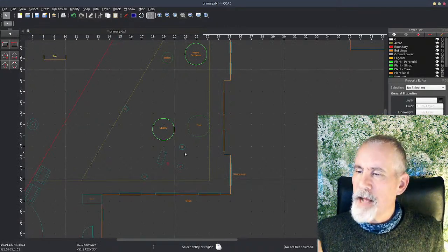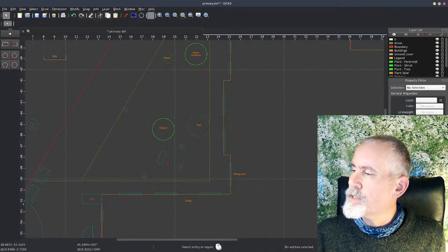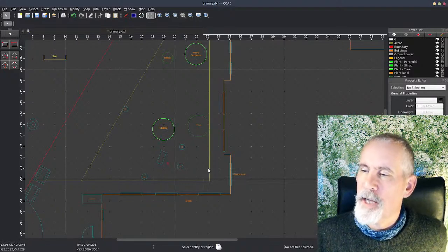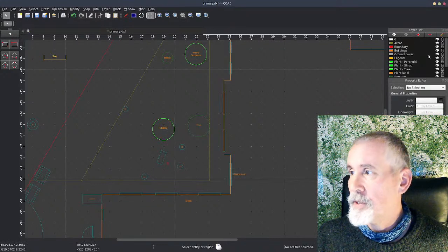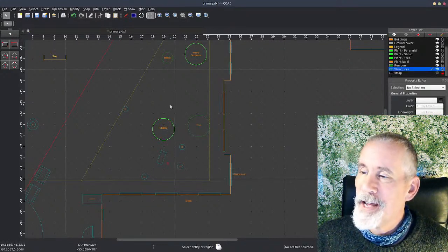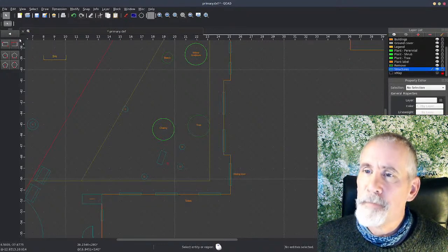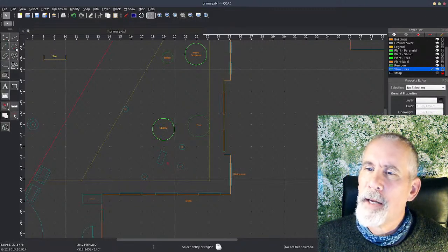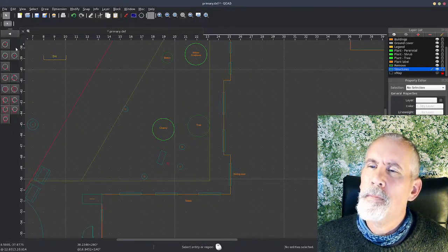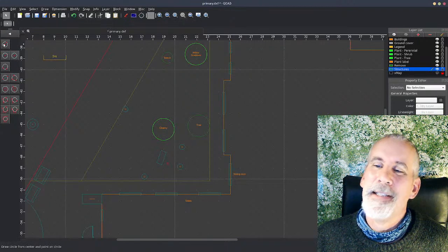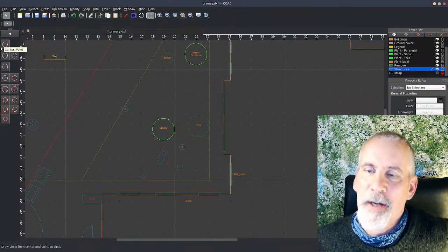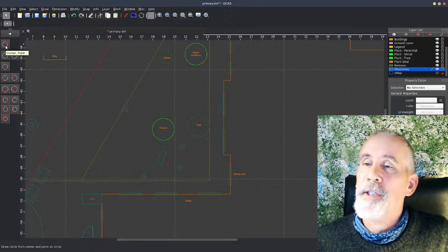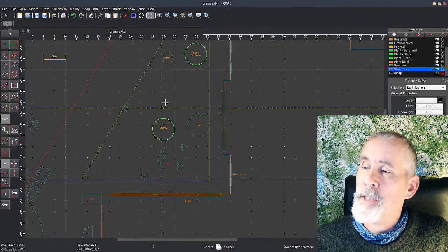And that's a block. So if you go here, you can see you've got a bench seating area, which is a block as well. So that's really nice. Next thing I want to do is to create a circle using the circle tool. There's loads of different options for creating circles. It's quite mind-blowing. CAD is quite incredible. I only ever use one, which is center point, so creating a circle from a center point.